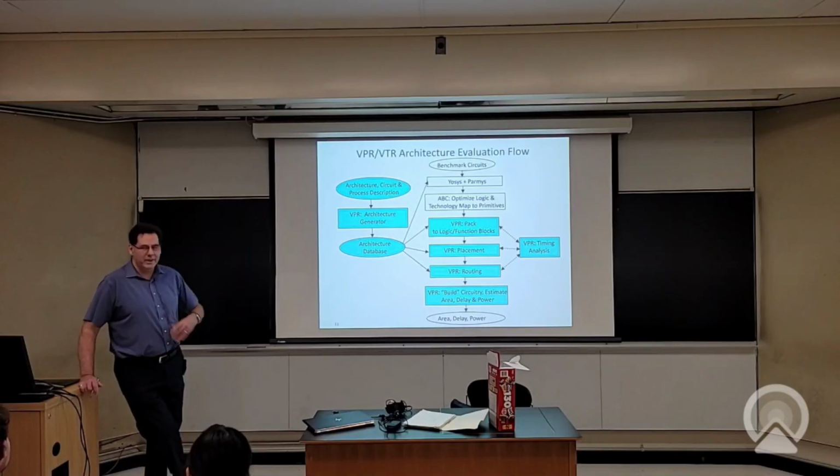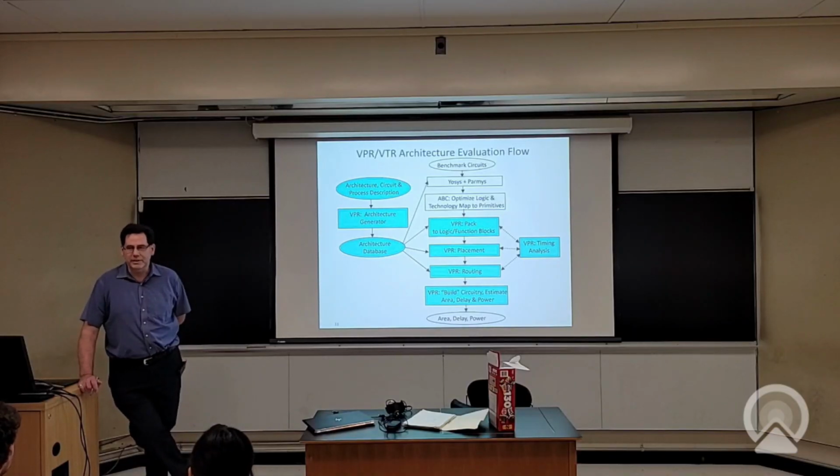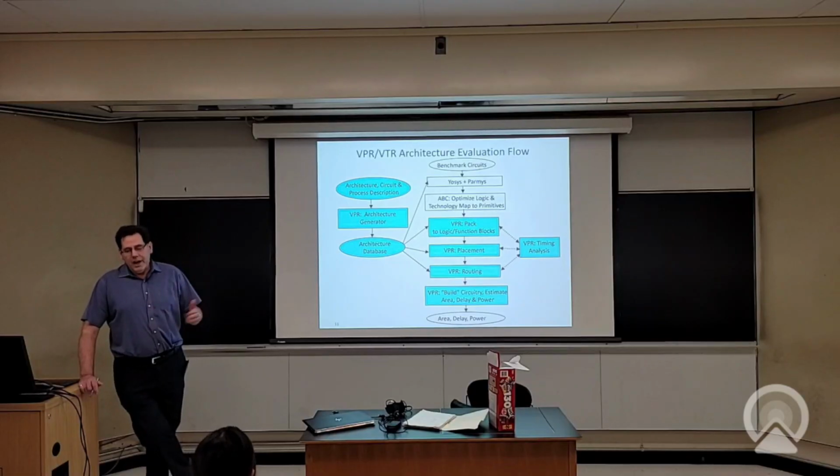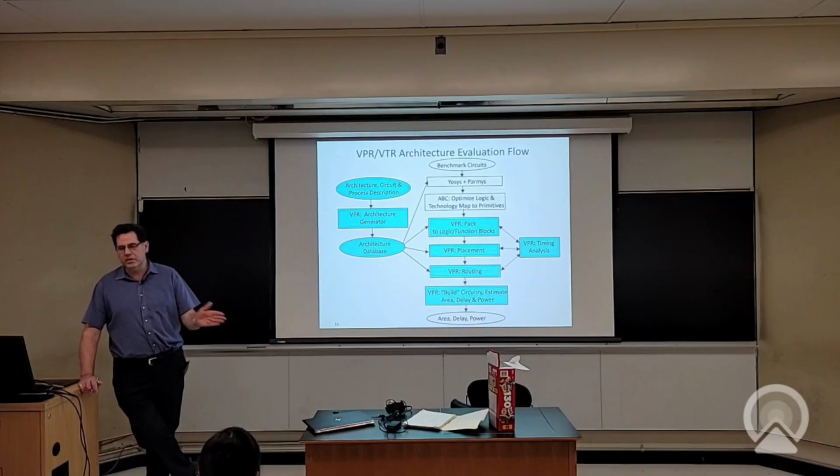So let's take the Stratix 2 paper that you're hopefully reading. Some of the big differences there would be 4-LUT, 5-LUT, 6-LUT, a bunch of different variations on 5 and 6-LUT, fracturability, how populated the crossbar is, which is another big one, and what the switch pattern looks like. And then changing the wire lengths, permuting the switch patterns: let's put a few more of this kind of wire in, let's put a few more switches in, let's take a few switches out.